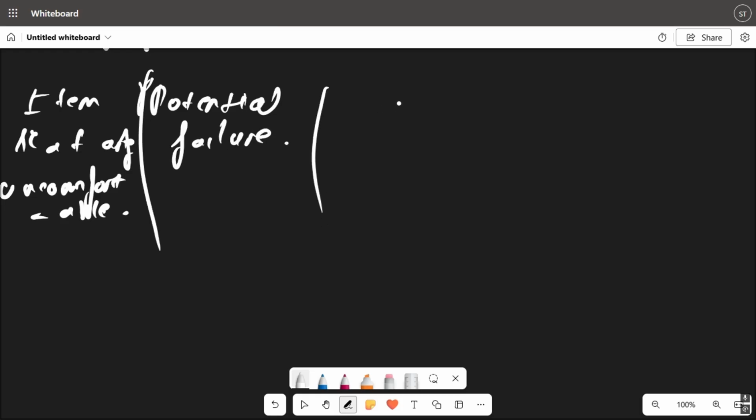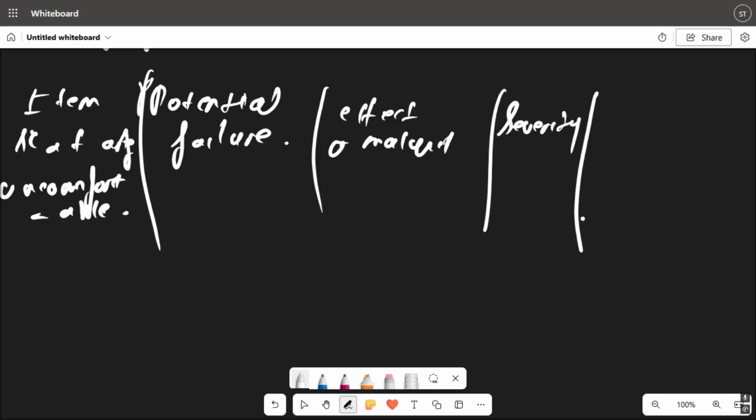And then you can write down here what is your potential effect. What is the effect analysis which can be done for that effect, based on which you can calculate your severity number. So the severity number, the occurrence number, and the detection number will be on a scale of 1 to 10. This is for severity. I'll get back to the total count, the RPN count, later.